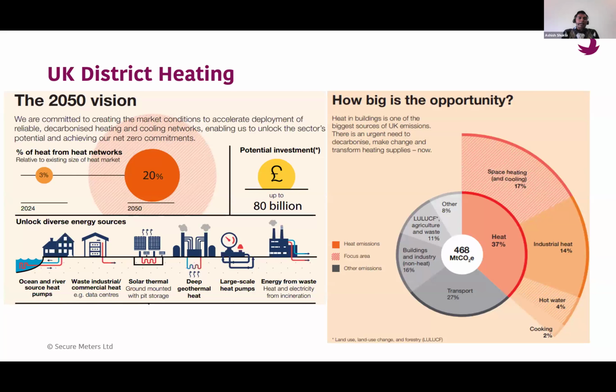So now what they're trying to do is, in place of heating it up to 90 degrees, they can heat up to 60 or 70, and then whatever delta is required, which they have to compensate, they can use some heat pumps. What a heat pump does is take air, and using electricity, it brings its temperature up.